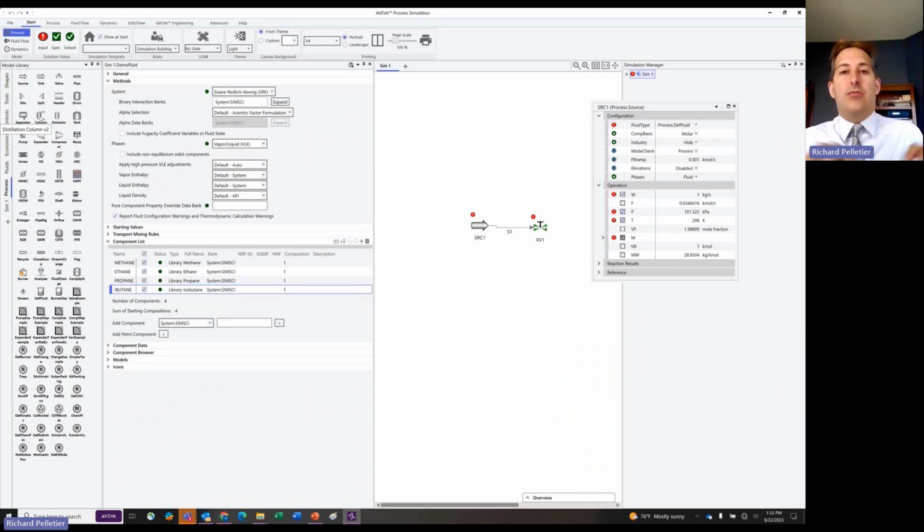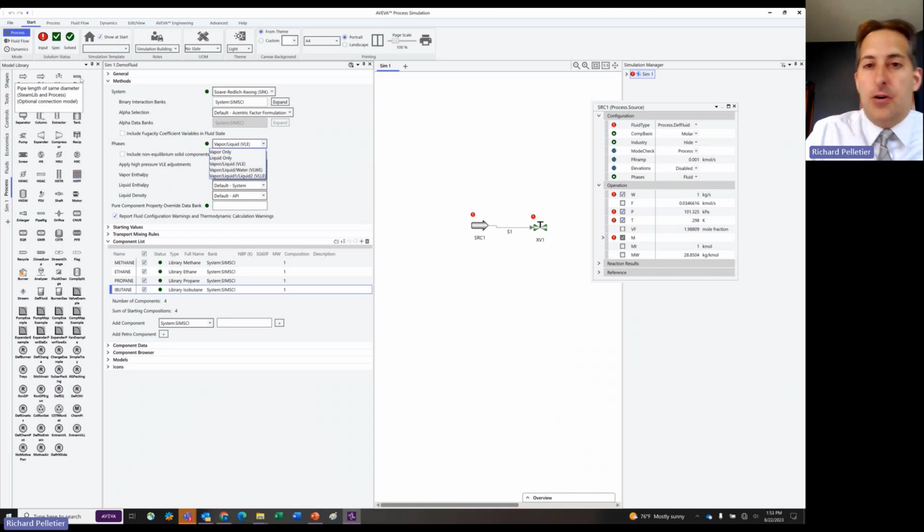Models like that, where three-phase separation can occur, will typically be the point at which you switch to a three-phase designation. Otherwise, you just keep it as VLE because, in a pipe, for example, all the flow that comes in is coming out at the same point. And so all the vapors together, all the liquids together, it doesn't matter. A drum even, all the vapor is going to go overhead, all the liquid's going to come out the bottom. It doesn't matter if it's two separate liquid phases or not.